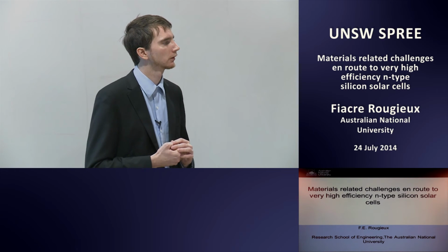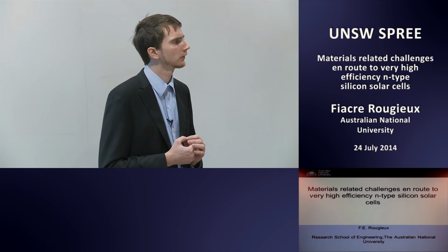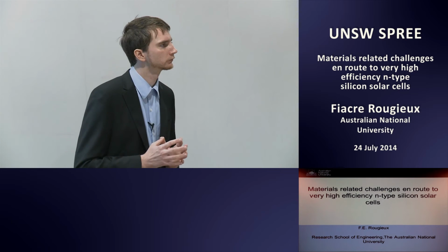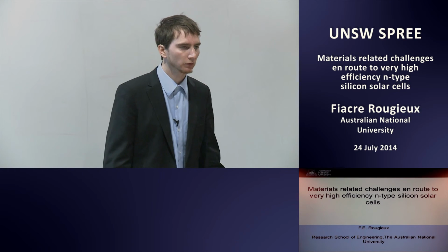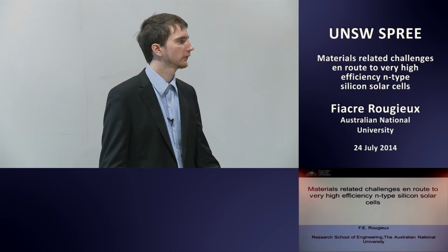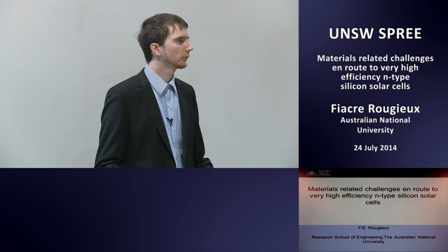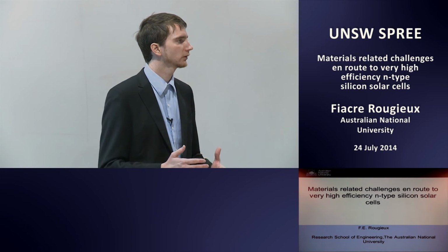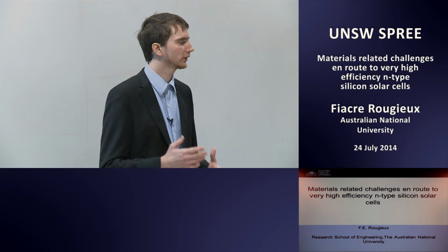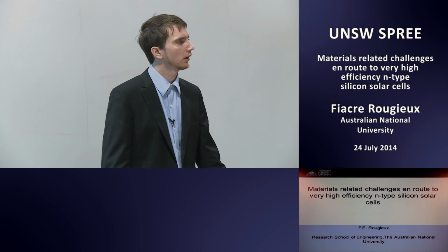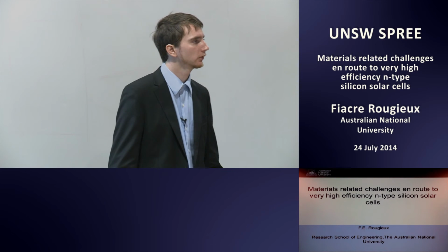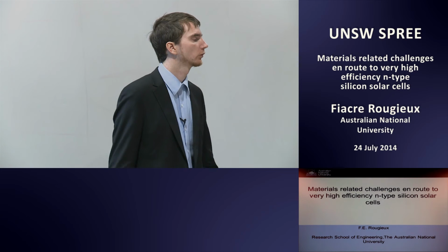Yes? So with your silicon nitride and aluminium oxide passivation on FZ wafers, were the lifetimes you showed as deposited, or were they annealed after deposition? So for the silicon nitride, it was the as-deposited passivation. For the aluminum oxide, we obviously had to do this 400 degree activation to activate the aluminum oxide, because it's atomic layer deposition. So it's after a 400 degree anneal.